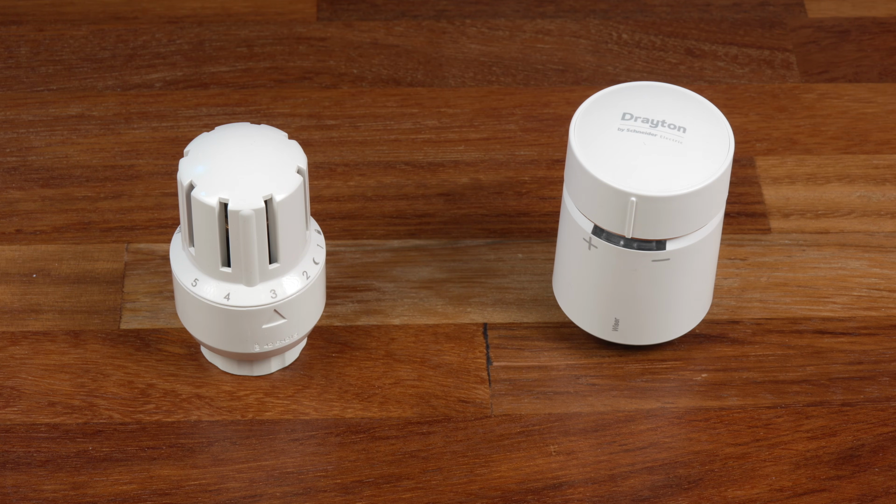I had a Tado smart radiator valve in my downstairs toilet, which is a tiny little room, and there were times where that room would get a little bit too cold and the smart valve in there would turn on the entire heating system just to heat that tiny little room up, and no other room needed any heat. Running a heating system in this way is very inefficient because the boiler can't dissipate all the heat it's generating into the air because only 1 or 2 radiators are allowing water through them.